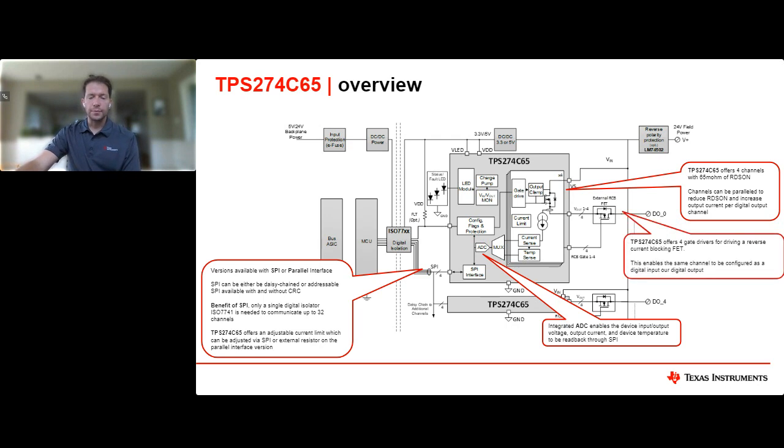And something else this device has is optional gate drivers to drive reverse current blocking FETs. So this really enables you to use this device in universal input-output modules, where this channel could be either configured as an input or an output. And last but not least, it also has a LED switch matrix for driving status LEDs and fault LEDs. So we'll get a little bit more into detail on some of these features.